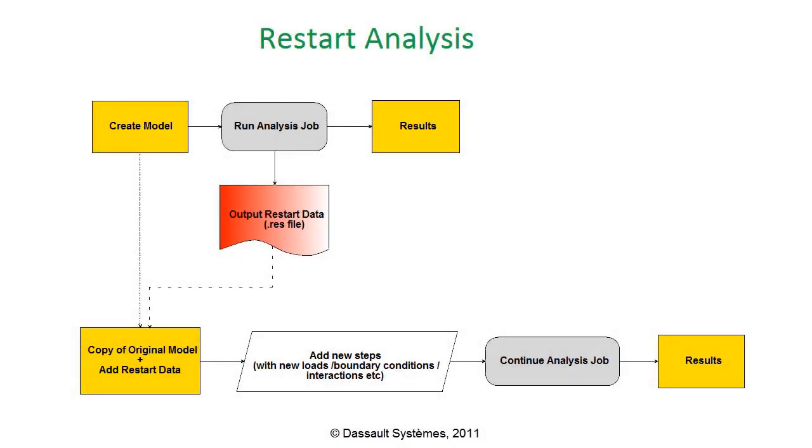Restart analyses are useful because they allow you to add another analysis step to a completed analysis job. This is very handy if your analyses take several hours or days to run, and you don't wish to add the new step to the original model and rerun the entire thing from scratch. It also sometimes helps to run a multi-step simulation in the form of separate jobs with restarts, so you can examine the results of each analysis and confirm that it is performing as expected.